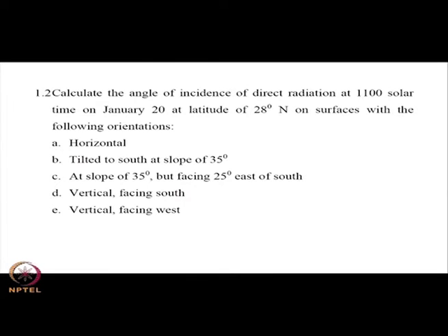So, naturally you can relate that the angle of incidence should be most favorable at around solar noon if it is towards south, and not so favorable, I mean larger, if it is off south.